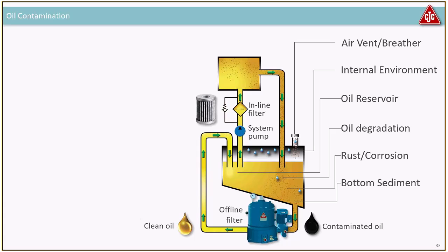You may think that it's only hydraulic systems that are breathing, but actually most systems are breathing because of the temperature changes. If a system is warm, the warm air takes more room, but when the air is getting cold and the oil is getting cold, it will take less room, and therefore it will suck in a new amount of air. And if that air is dirty or wet, then you'll get the dirt and water into your oil system.